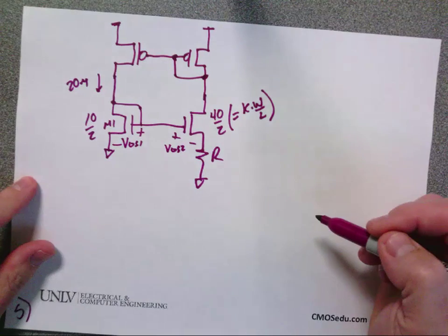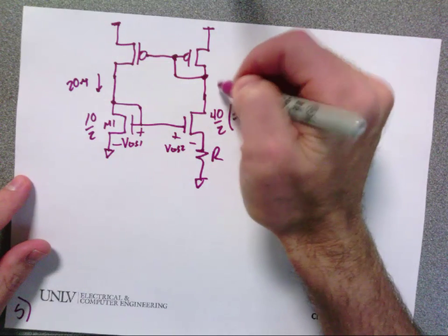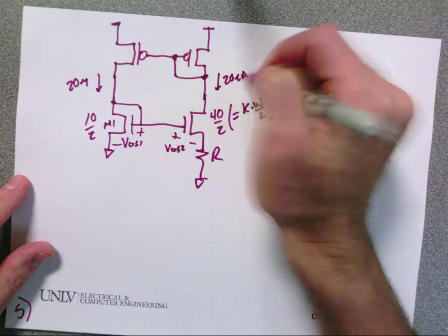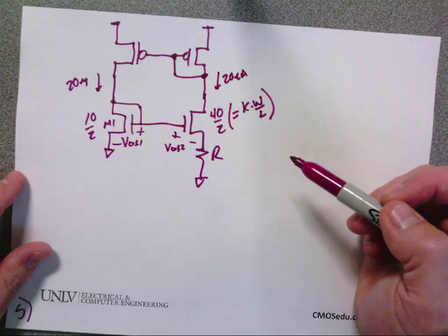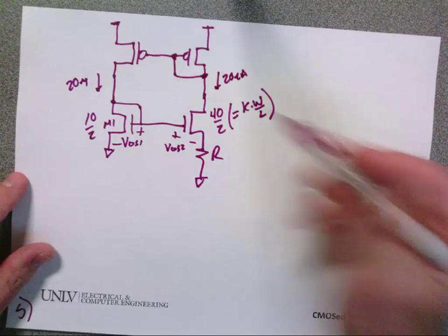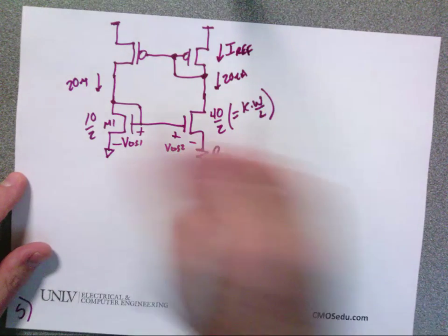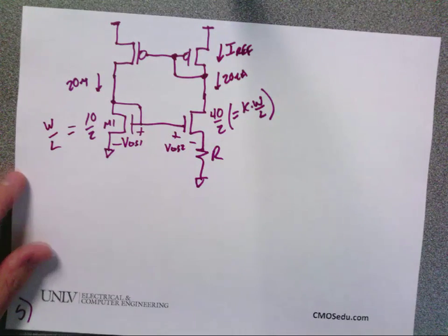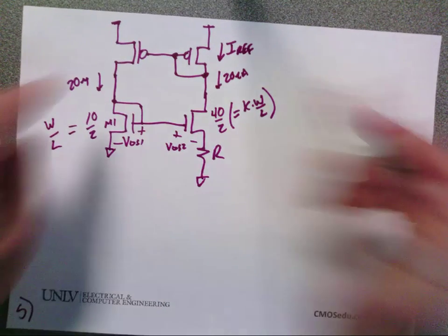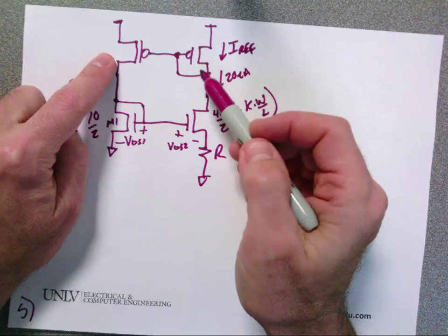And I'm going to put a current mirror just like this. So now, if I design this right and I get 20 microamps flowing through this, it mirrors over here and I get 20 microamps flowing through this. But I'm going to just leave it as Iref for now, and then we'll derive the general equations, and I'll label this as W over L. Now these sizes I want to be the same. I'll set them to my PMOS size, okay?